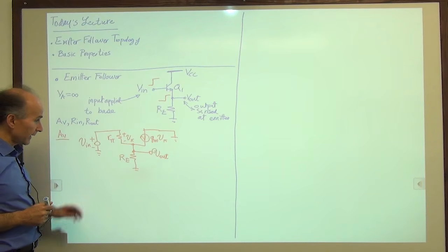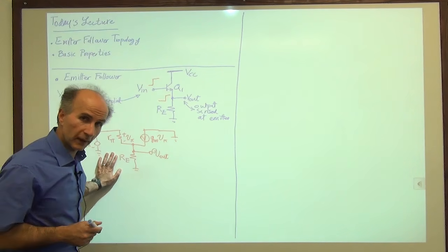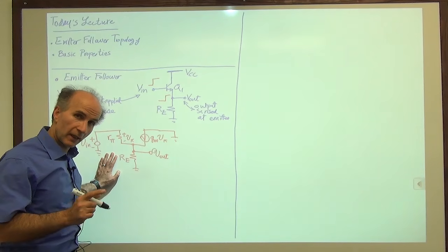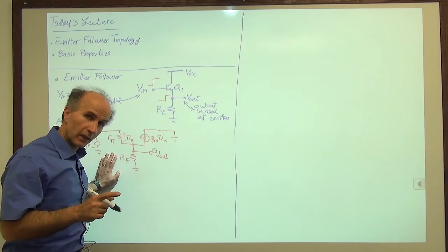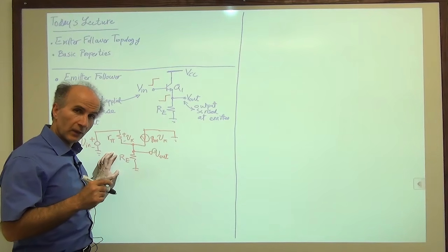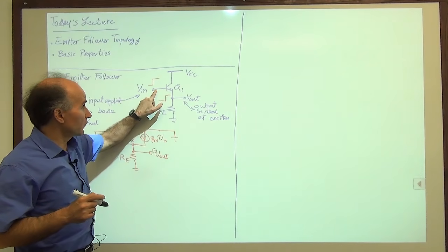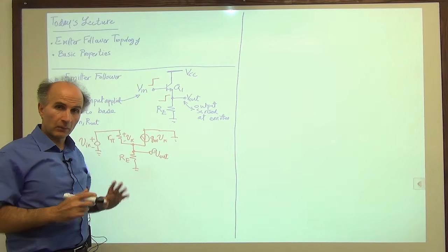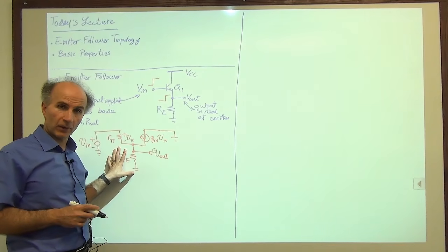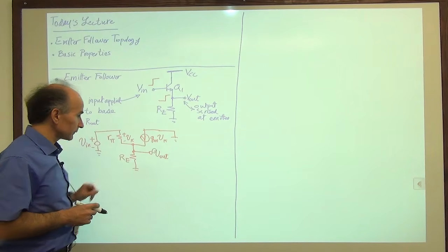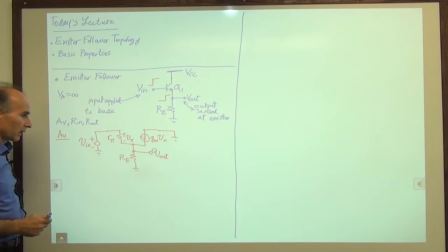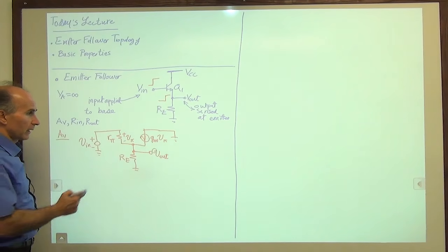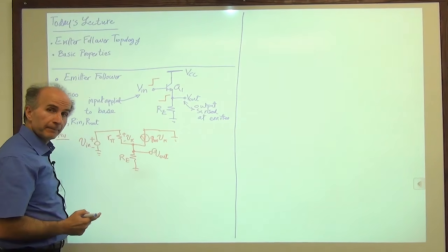Okay, in fact, this analysis is very similar to what we did for the common emitter stage with degeneration when we wanted to find out how much of the base change goes to the emitter, right? But again, we'll just try to attack the problem directly here. Okay, well, shouldn't be that hard. Again, we would like to eliminate V pi.